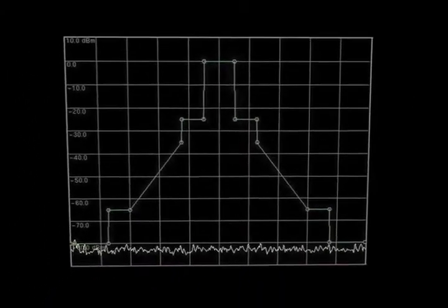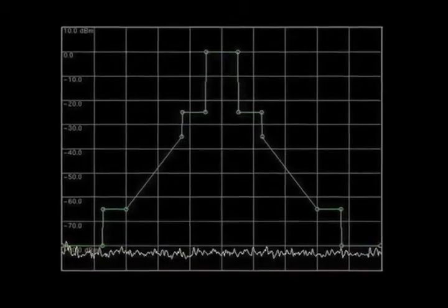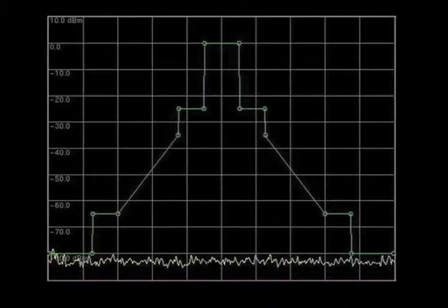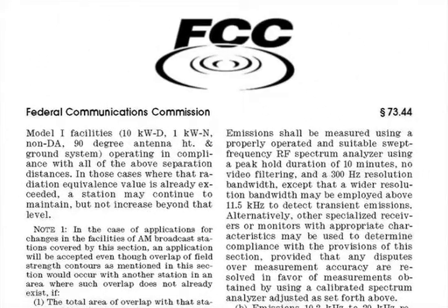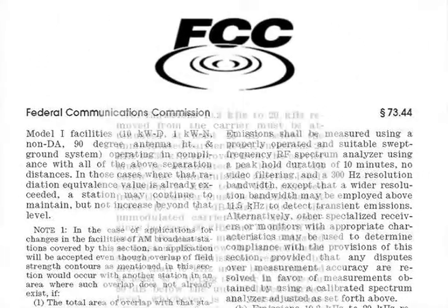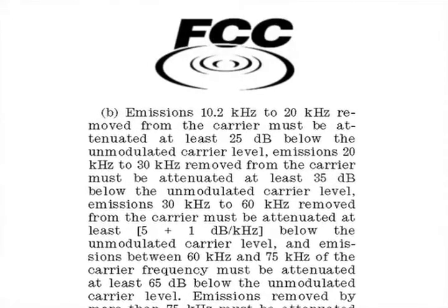On a spectrum analyzer display, limit lines are frequently used to show the expected shape of a modulated signal. Most signal standard documents contain information about the shape of the over-the-air signal in the form of a mask definition. The easiest way to create a limit line based on the standard values is to create a table that shows